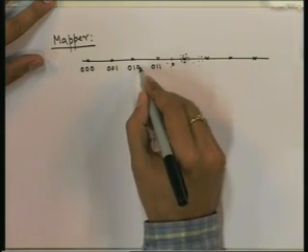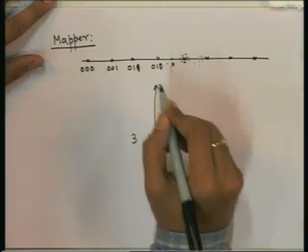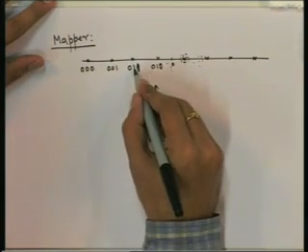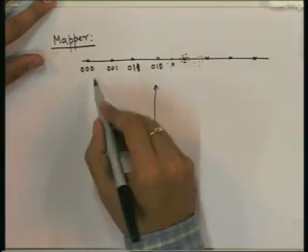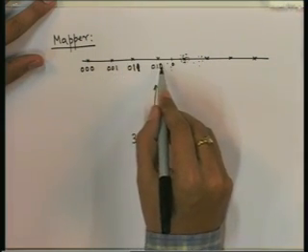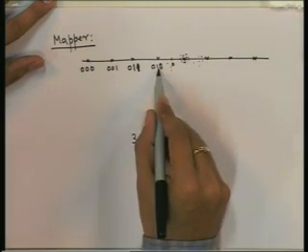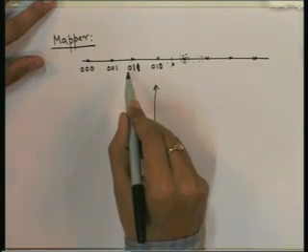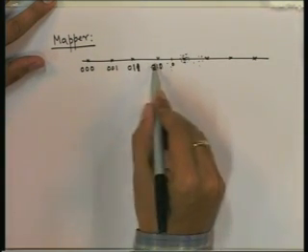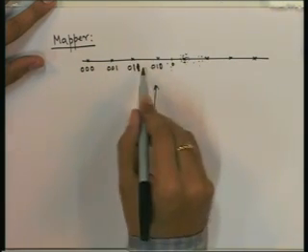Sorry, this is 1 1, this is 1 0. So, this is different from the usual encoding. Usually we have 0 0 0, 0 0 1, then 0 1 0 and 0 1 1, but here we have 0 1 1 and 0 1 0. The difference of bits between any two neighboring points is only 1 bit. At a time only 1 bit is changing.